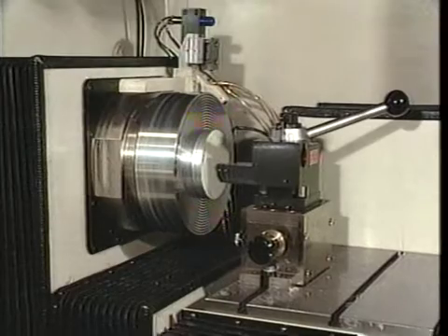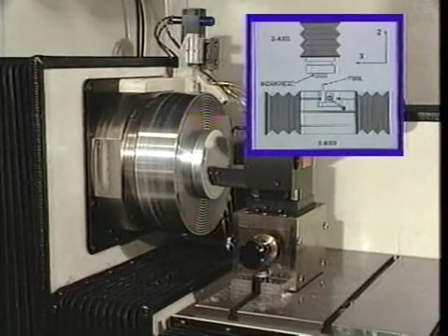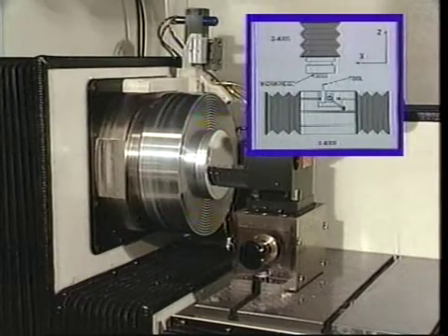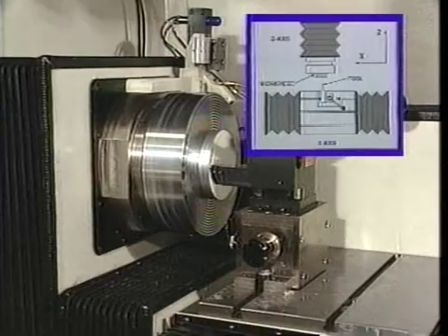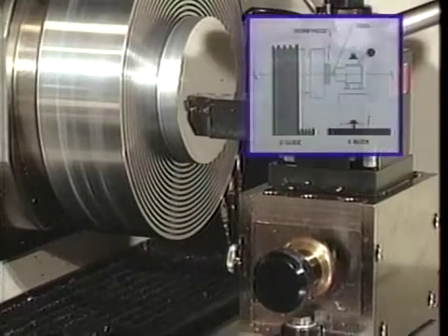This ultra-precision lathe or diamond turning machine achieves two-axis motion through two orthogonally configured hydrostatic bearing slides. The spindle and workpiece ride on the z-axis slide.